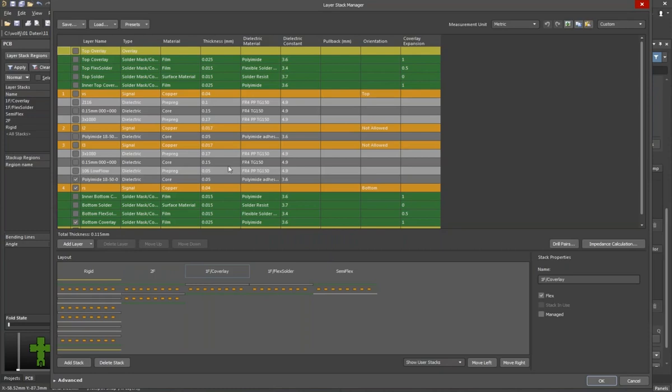And in the board shape, to make a Flex-Rigid design, you can define where my rigid and my flexible areas are. To do this, I already created different layer stacks. So this is the setup for this sample, and this is a layer stack you probably will never find on our website, since all of the offered technologies are being used here to show it in one sample. So we have our rigid stack-up. It's a 4-layer stack-up with different materials in it.